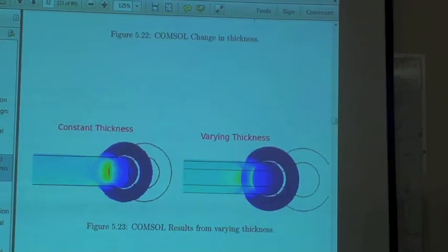But if I increase the thickness of just this ring here, then this point is virtually not in contact with anything. So I reduce the contact stress, but I've only increased the material a little bit, just around where the ring is. I didn't have to increase the whole thickness of the beam. This is essentially the same analysis, so it definitely helps optimization.